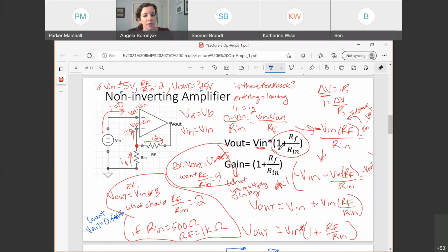Yeah, the gain for this always has to be greater than 1, because I can't have negative resistors, and there's no such thing as that. The least I can do is 1 plus 0, but I can't even really get 0. So you can't multiply by something less than 1. Most of the time you want to make something bigger, like you have a voltage in, make it bigger, like more money, right? More voltage, more money. Most people like that. But if you do want to make something smaller, like to fit in a graph of a smaller scale, you can't do it with this guy.